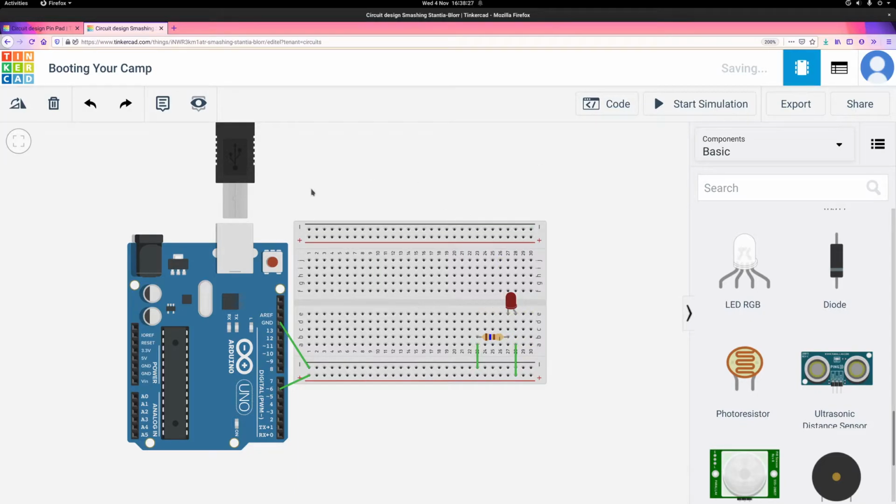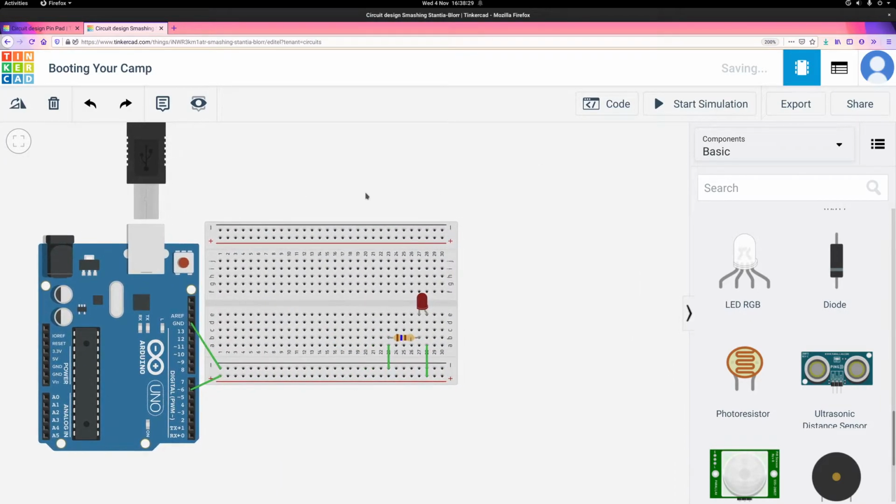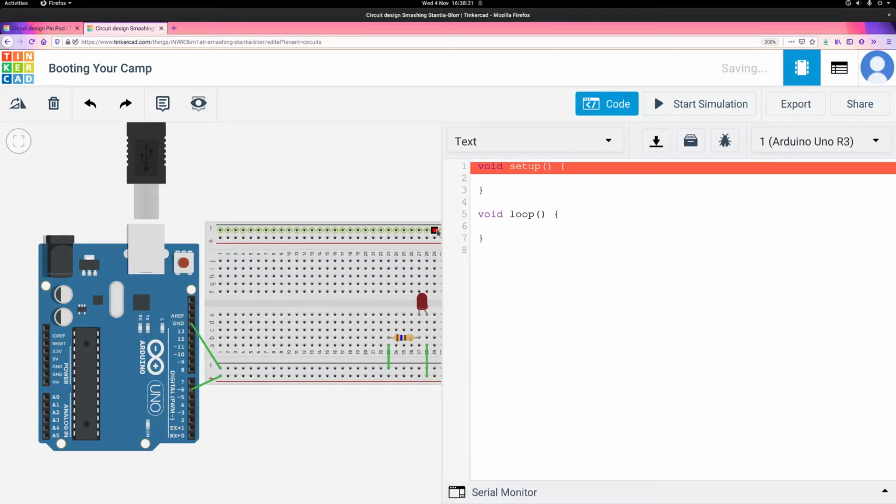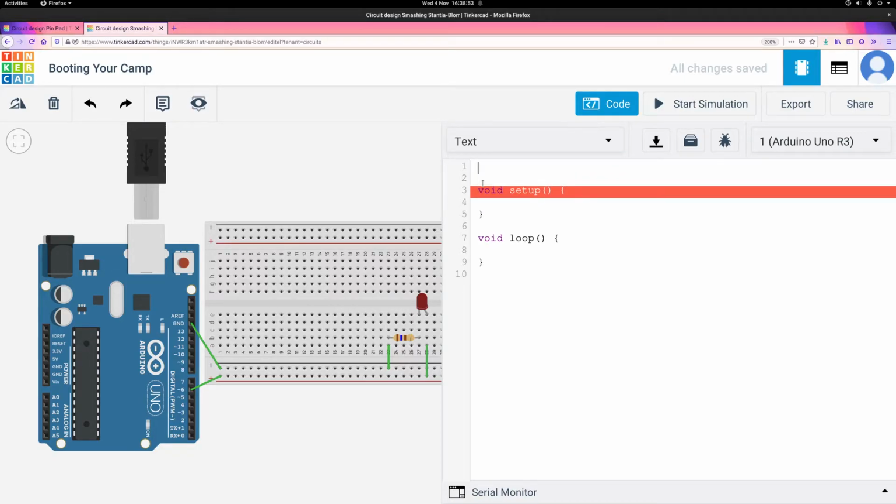So, to show that in action, we'll pop our code back open again, now that we have it connected up in a sensible way. Something that's sometimes nice to do, and this is an optional part, you can define a variable that stores your pin assignments. So it tells you what pin is responsible for what. It basically just gives a number a nicer name for you to work with. So I'll do that just to show off how it works. The recommended way to do this in the Arduino language is probably to do something...